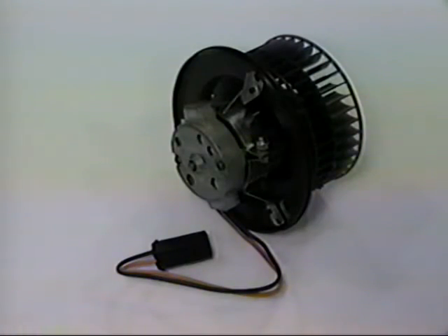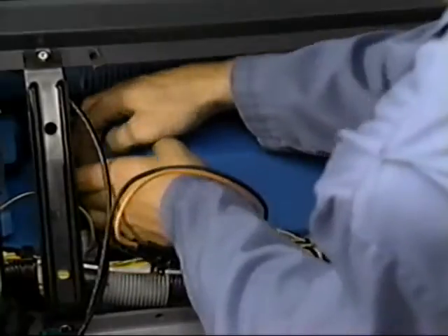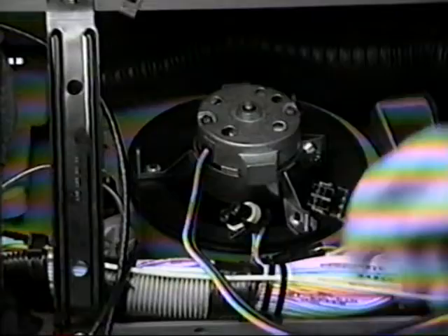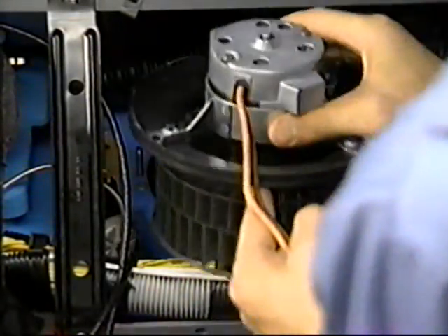The heater AC unit features a single blower motor, which draws 21 amps and is rated at 10,000 hours. It's easily accessible after the motor wires are disconnected and the housing cover is removed. The motor lifts out of the housing after removal of the 3 nuts holding the motor to the unit.